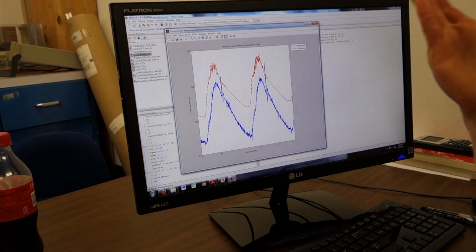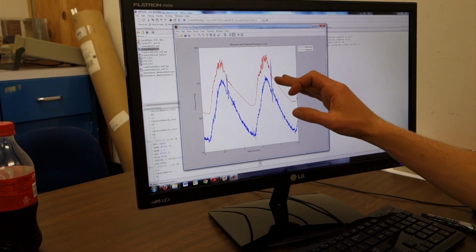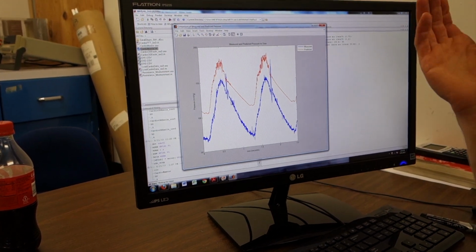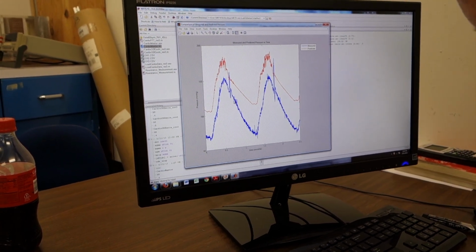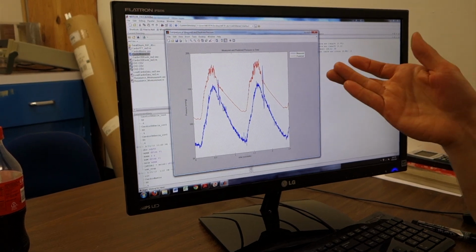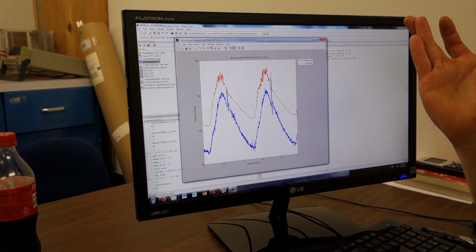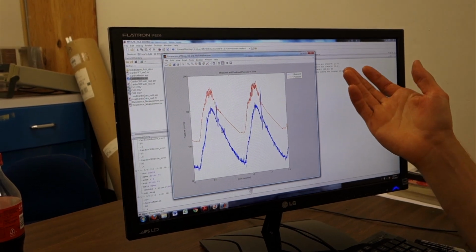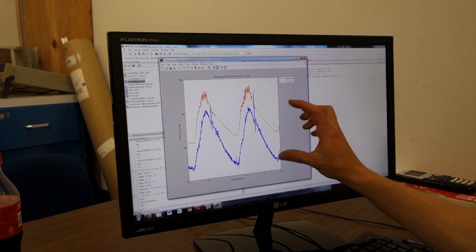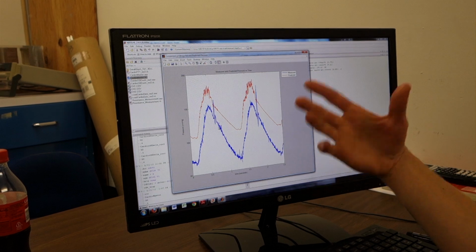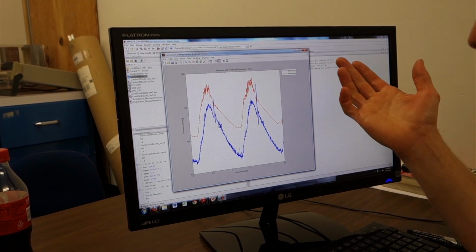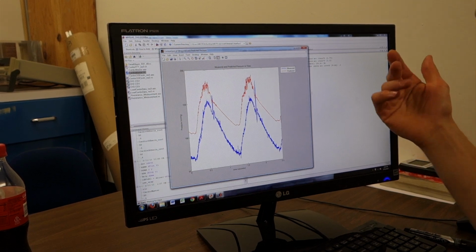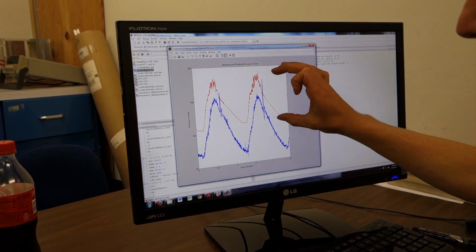So my question is, what do we change to tweak the mean value to match the experimental mean value? And the logic behind this is to think of a time average signal. Remember that delta P equals Q times R. The Q is our input. The Q is known in this problem, and the only way to get a lower pressure is to have a lower resistance, because Q is a constant. So I'm going to go back and try to tweak my R1 plus R2 value by decreasing it a little bit to try to shift the mean value down.